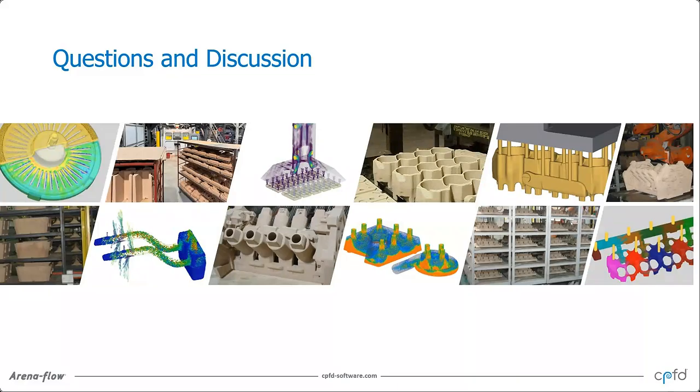If your magazine is depleting between blows, it could be the opposite scenario, where you have small cores compared to the magazine. You don't refill the magazine every blow. And so how is core filling quality affected by sand magazine level? You can do all those sorts of things now with that new feature.